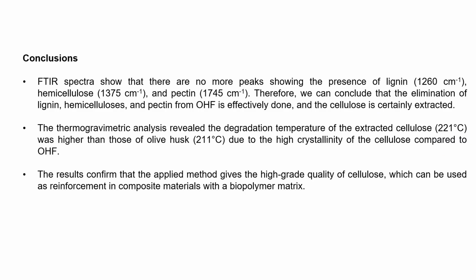As conclusions, we can say the FTIR spectra show that there are no more peaks showing the presence of lignin, hemicellulose, and pectin. Therefore, we can conclude that the elimination of lignin, hemicellulose, and pectin from olive husk flour is effectively done, and the cellulose is certainly extracted.